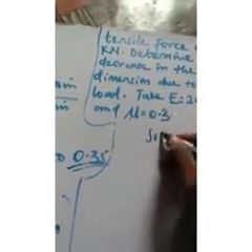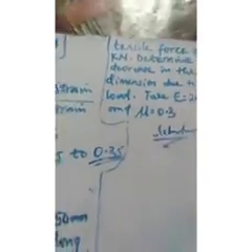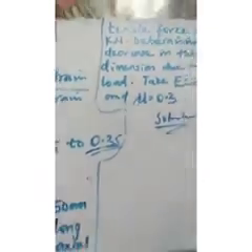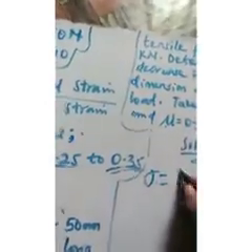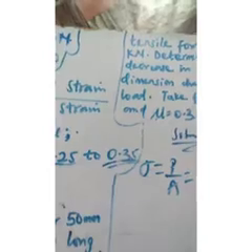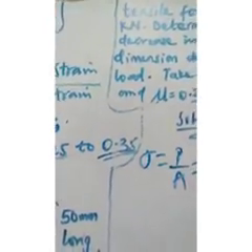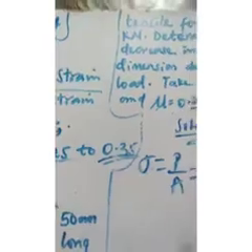So the solution, looking at this example, is very simple. First thing, you want to get this lateral strain, so you need to get the axial strain. And you know your axial strain you can get from your stress. Stress is equal to load over area. And what is your load in this context? Your load here is the tensile force, 250 kilonewton, right? So you have your 250 kilonewton and you have your area.